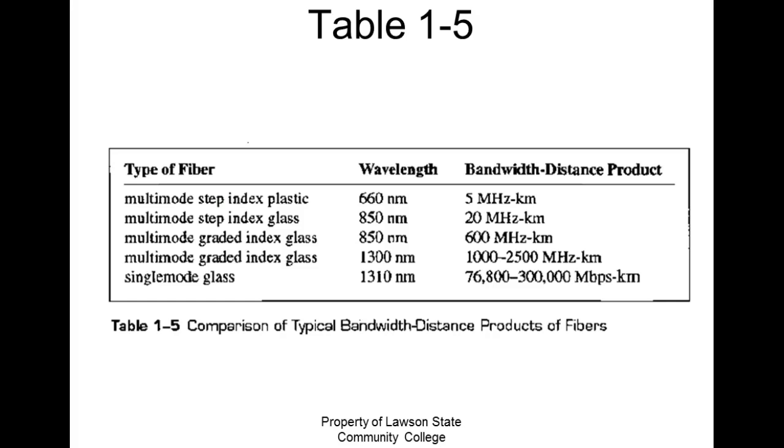So that means if you had a micrometer out and you measured this glass, the single mode cable would measure exactly the same as the multi-mode cable. So what they did is they came up with industry standards on how they do that outside jacket. So they have color codes for the different jackets that we have, and that's about the only way you can identify single mode from multi-mode.